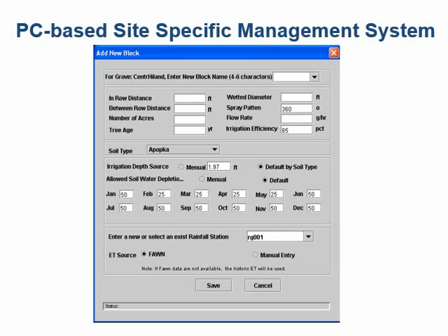Now, rainfall. If you have a large grove, you may have many sections that have one rain gauge associated with those different irrigation zones. So one rain gauge may supply information for a number of zones, and that's what we have here. You can enter a number of rain gauges and then tie it to a specific block so that you only have to enter the rain for that rain gauge once. Then you select your source through FON, and if you select FON, it'll ask you for the FON station you want the data to come from.